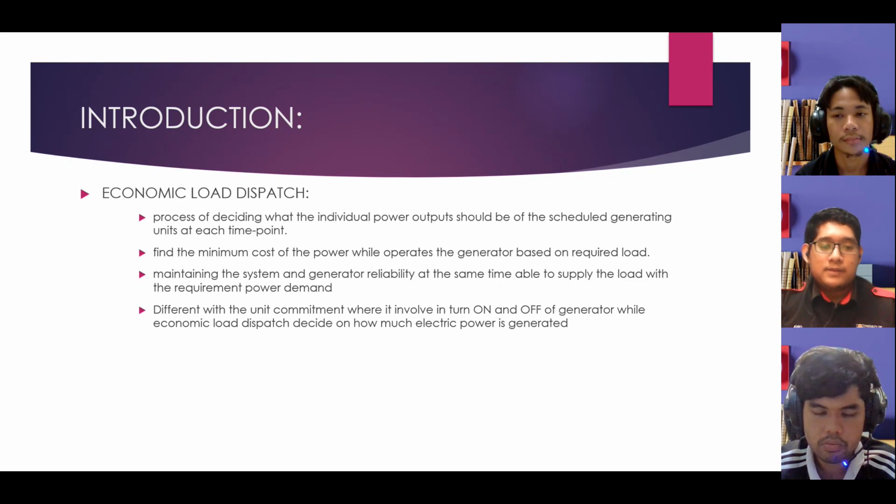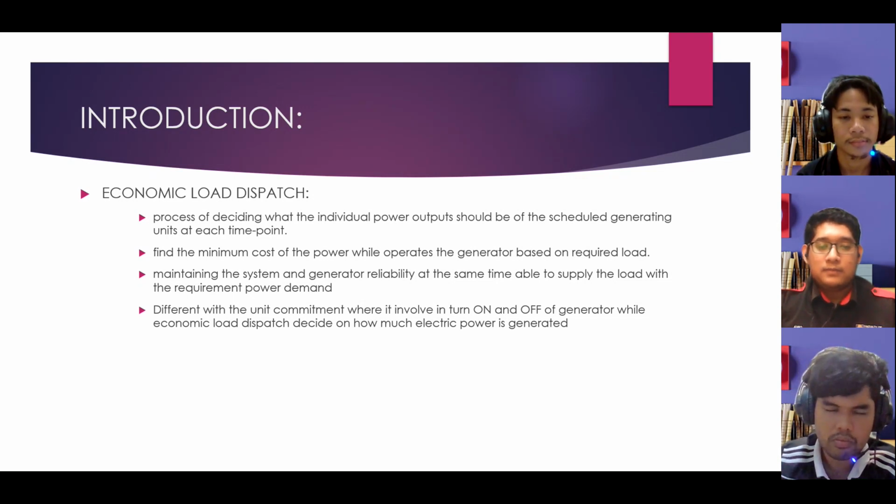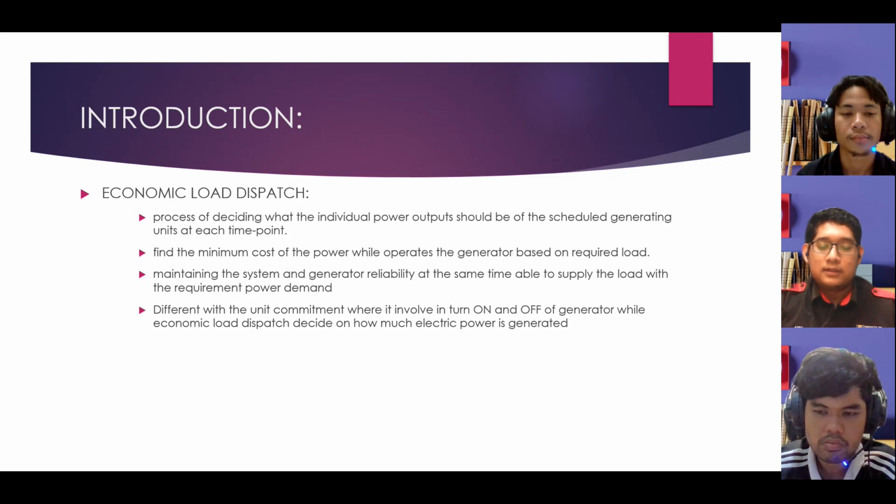The economic load dispatch is a bit different from the unit commitment, where the unit commitment is the turning on and turning off of a generator. Meanwhile, the economic load dispatch decides how much electricity needs to be generated by the generator.